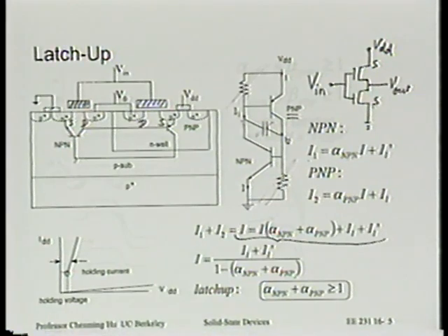Well, it turns out the answer is not that in this CMOS technology, the parasitic bipolar transistors are lousy, and therefore don't have very large alphas. That's not a correct answer, all right? Their alphas are very good. But just to force that issue, let me ask you to perform this mental experiment.